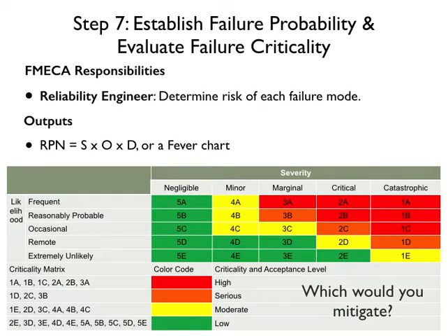And then another thing about this chart: when actually developing the FMECA analysis, it's good to show an image exactly like this in the section where you describe your methodology, so how you're going to execute the FMECA, showing essentially the image here with the different risk categories in it.